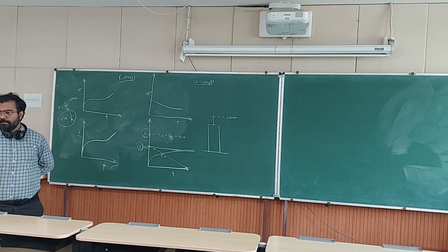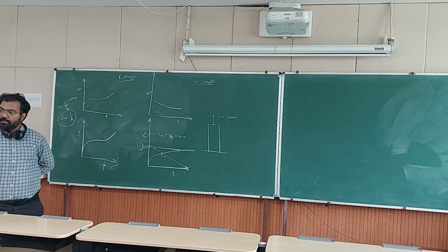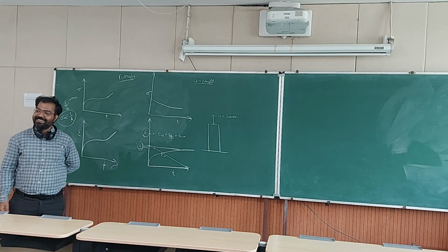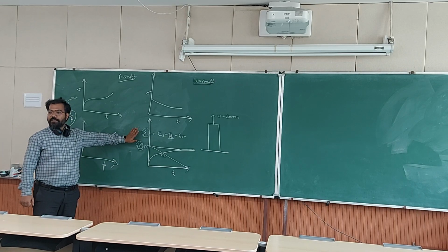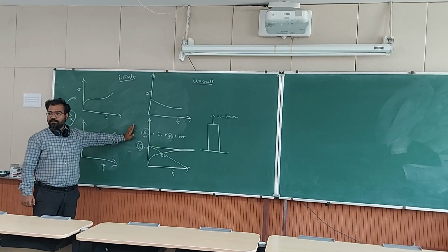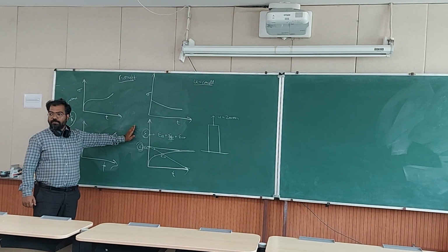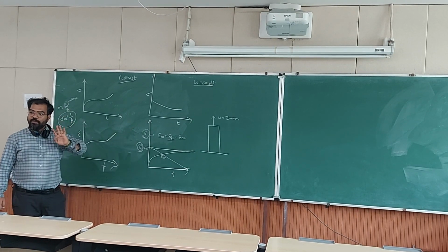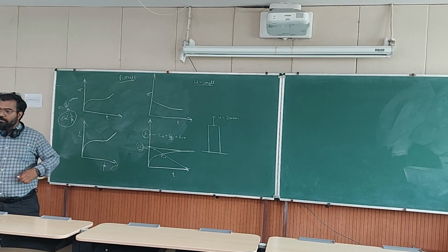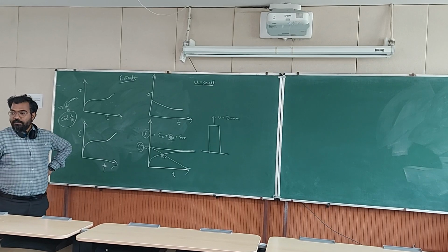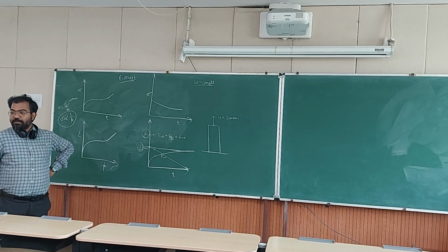No? Yes? What does it mean that elastic strain is decreasing? Tell me, what does it mean? Because the total has to be constant, so it is constant, and creep strain has to increase with time. We understood that for the total to remain constant. But so now you are saying that elastic strain is also behaving in a time dependent way. Yes. But elastic strain is not time dependent. So why is it happening?